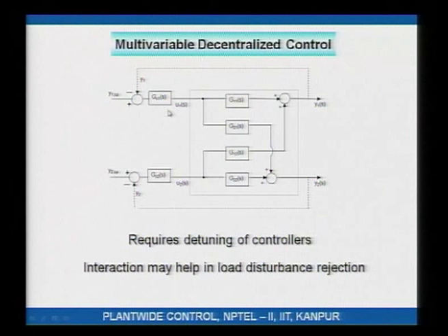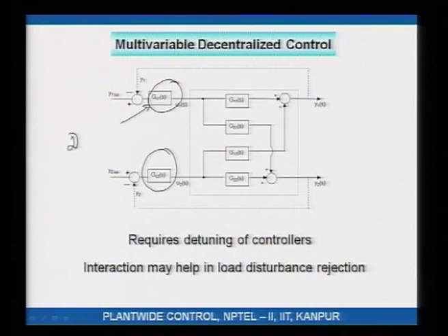Now the question is, how should you detune this? Detuning is necessary. How do you detune this? Detuning by how much, and by how much should you detune this controller? That is the basic question.